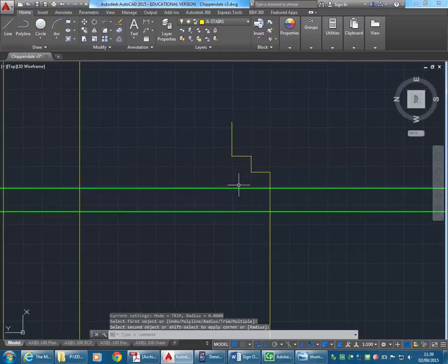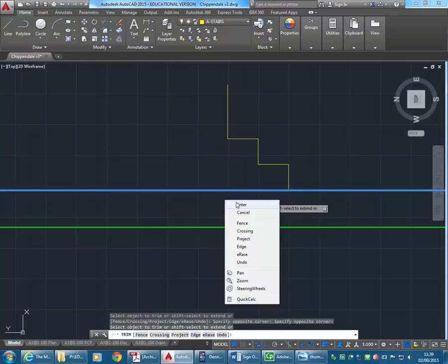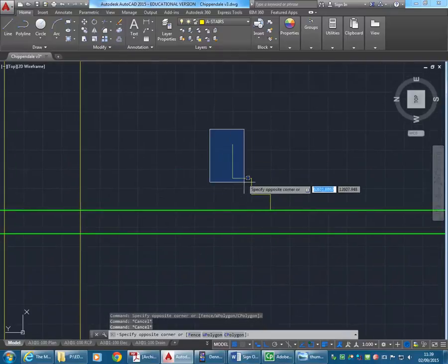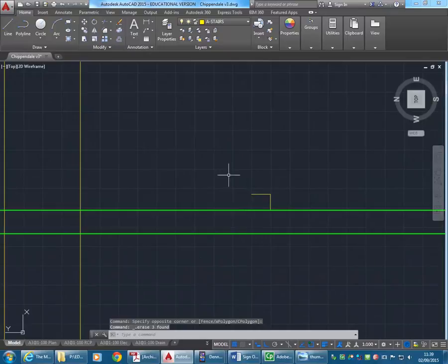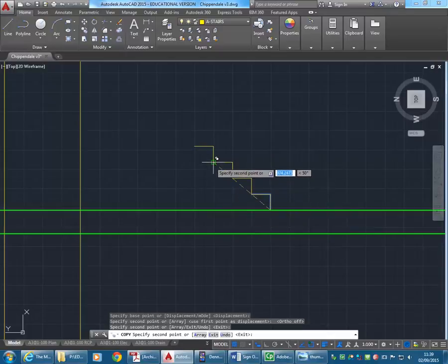But what you realise before long is you're basically just making the same thing over and over again. So I'll trim that back. And you can see there we've basically got this L shape. So that's a riser height and a tread width. So I'm going to delete the others. And just with that L, exactly. Yep. And that's how you do stair design when you're doing it in 2D. That's right, exactly. So once I hit the landing, I know I've got that first flight done.